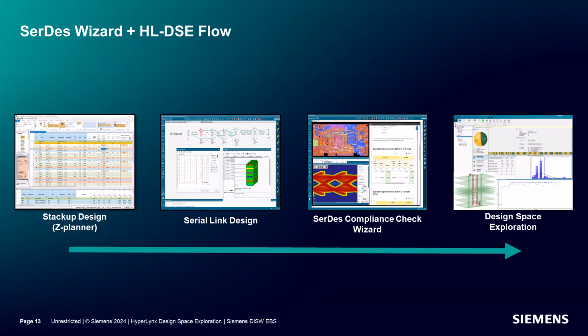Using this utility allows the design team to minimize risk of high-speed design errors from the start, in the schematic stage, before layout even begins. From here, typically one would run the wizard next, and the wizard would produce an informative report with the simulated results of each combination of these varying values.